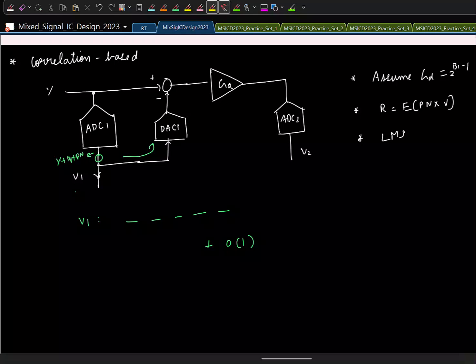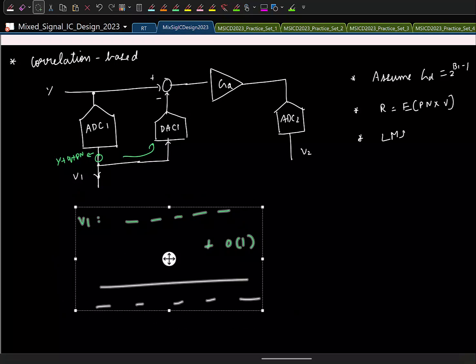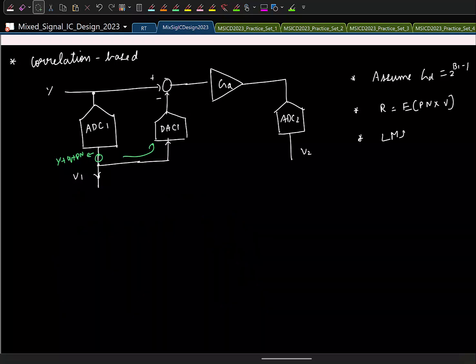So of course one thing is what he suggested, you can add directly to the ADC output, but that means that this can become an extra 1 bit, right? The summation. So which means the DAC has to handle that many bits. So where else can I add? After the DAC you can't add, right? That is not trivial.